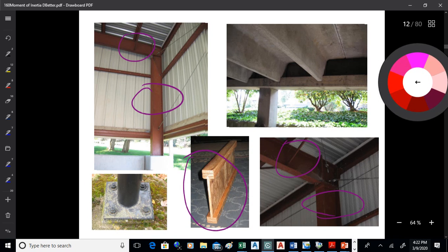There's a typical joist for a house now. They used to be 2-bys that you'd use. Not anymore. Now they use this TJI stuff, which is really just an I beam. You get that kind of cheap press board in there. You can save a lot of money with the weight and material on that. And you've got laminated plywood flanges on those things. There's some double T-beams, big massive concrete T-beams. There's a tube being used as a column.